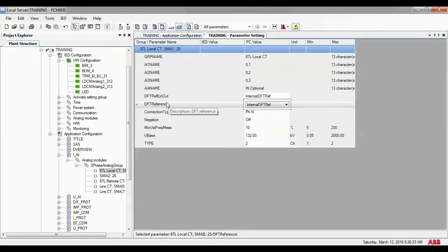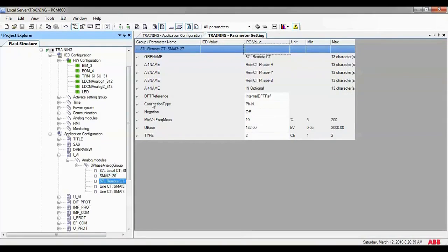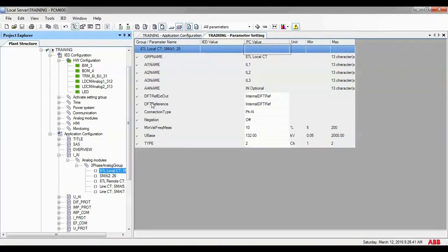You will find this for the single settings, while all the other blocks just have the word DFT reference, which is the discrete Fourier transform. The block always senses the signal, and it can read RMS and DFT. The difference between the two is that RMS will include the harmonics and DC offset, while DFT tells you only the fundamental.